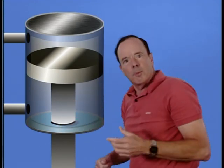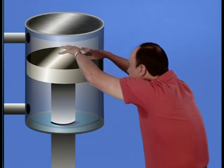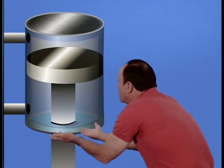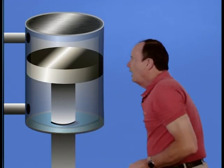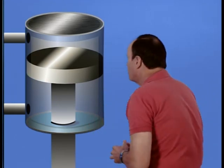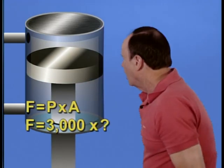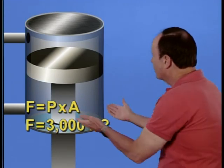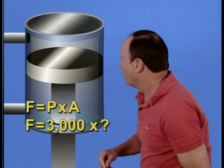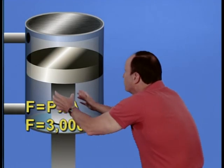And they tell you the piston has a surface area of 3 square inches on this side, which is the extension side, and it has a rod with a cross section of 1 square inch on the retraction side, which would be this other side here. And what they want to know now is how much force this actuator will be able to produce when you're retracting. Well, let's go back to our formula. Force equals pressure times area, and the pressure is 3,000 psi. Aha, but be careful. What is the area? Well, the piston has 3 square inches total, but there's a 1 square inch rod.